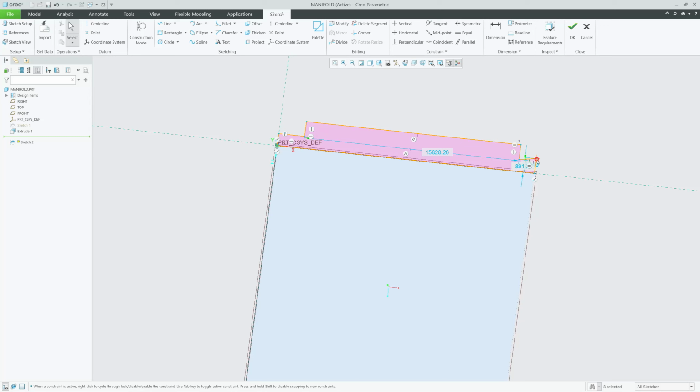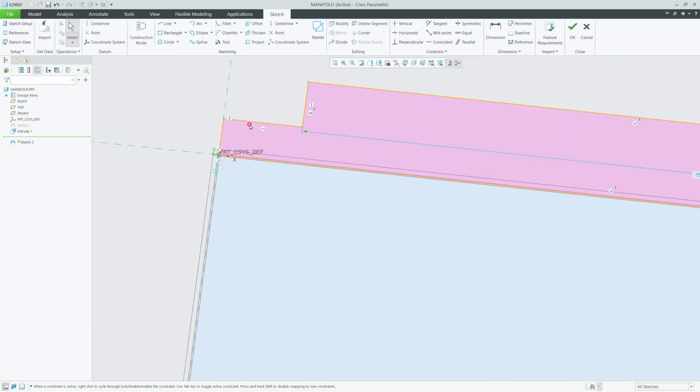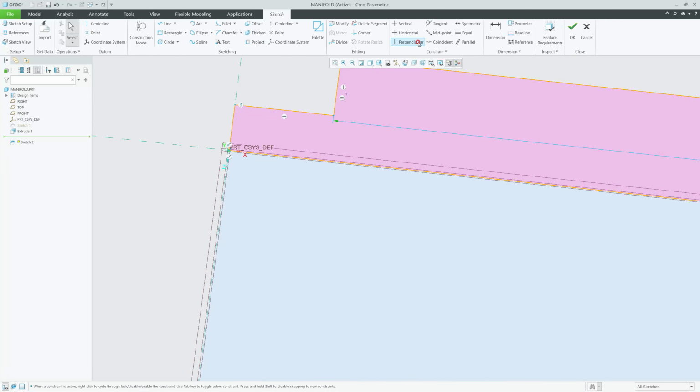Okay, I can set the dimensions properly. So, because this is in micron, the dimensions we can give, this should be 1 micron, so we'll give it 1000. This should be again 1000.